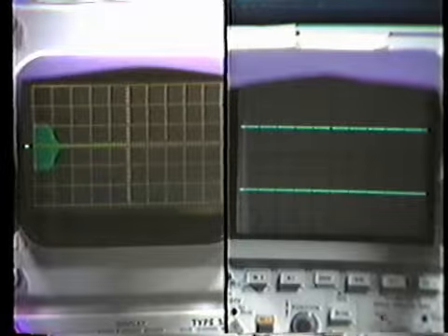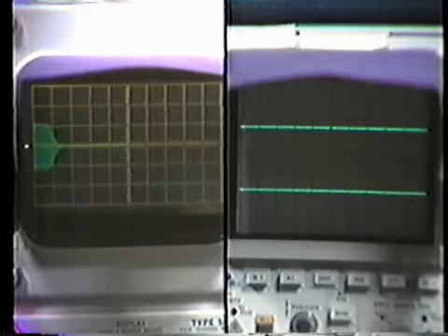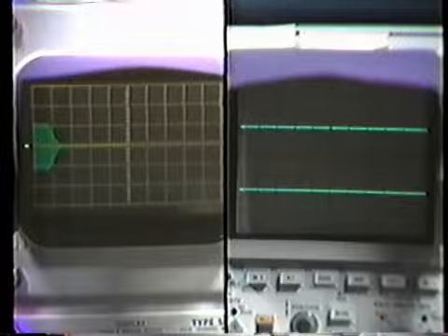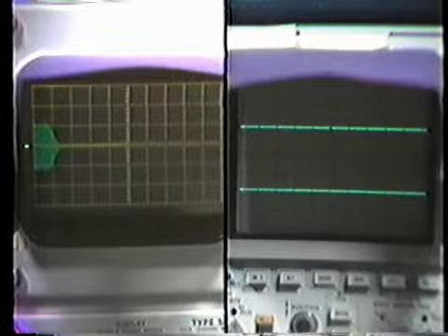Now what we would like to demonstrate is the effect of changing the sampling frequency. And we know that the effective filter cutoff frequency is tied to the sampling frequency, and for this particular filter corresponds to 1/10 of the sampling frequency.